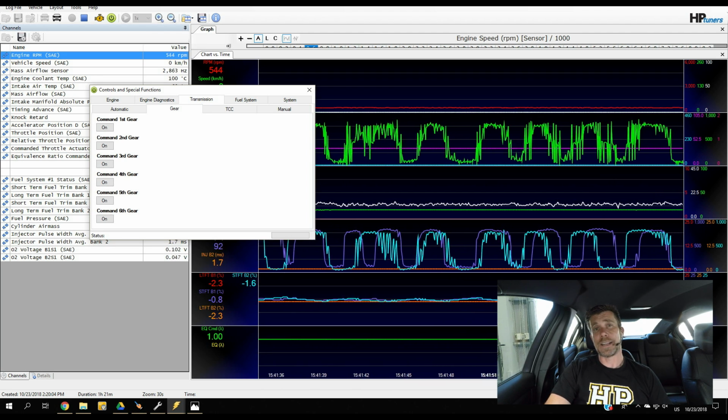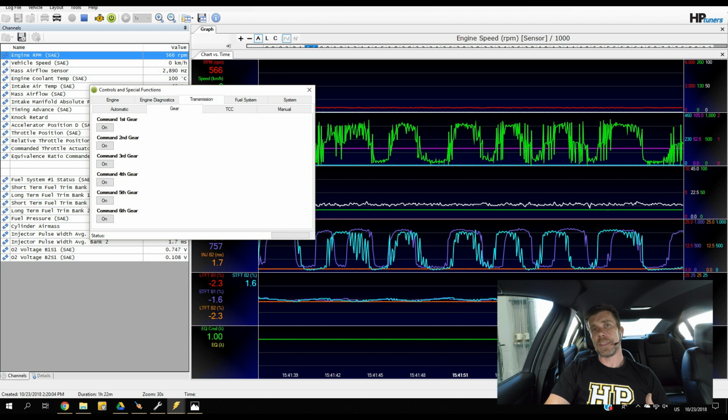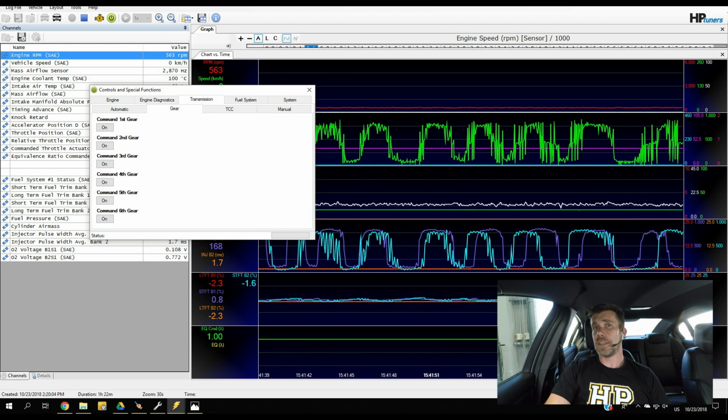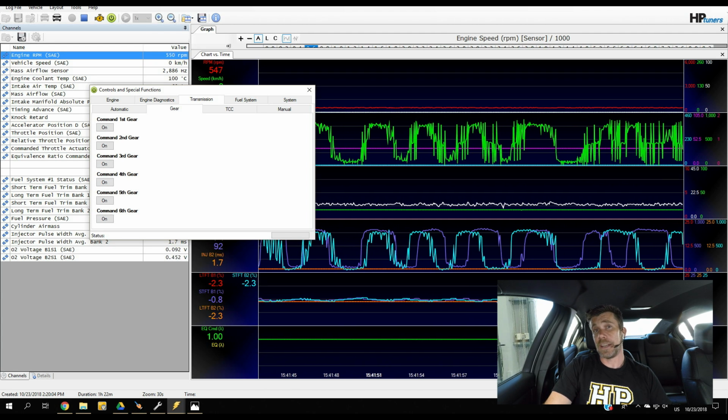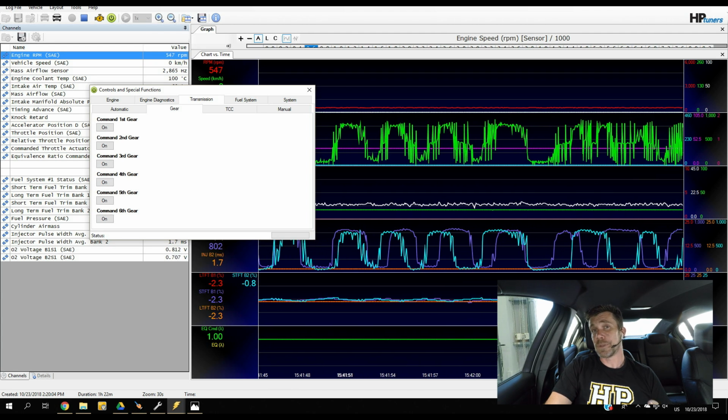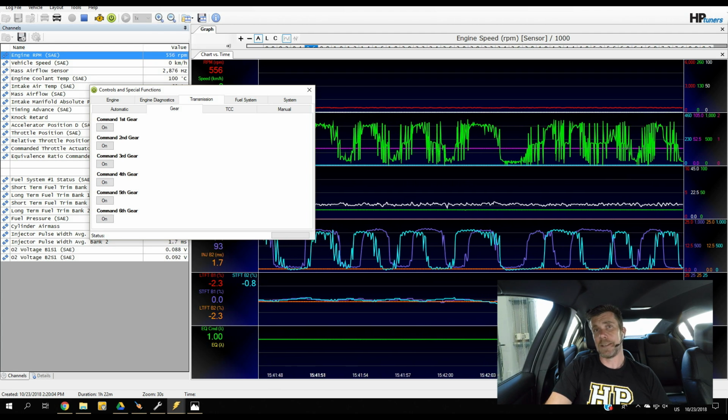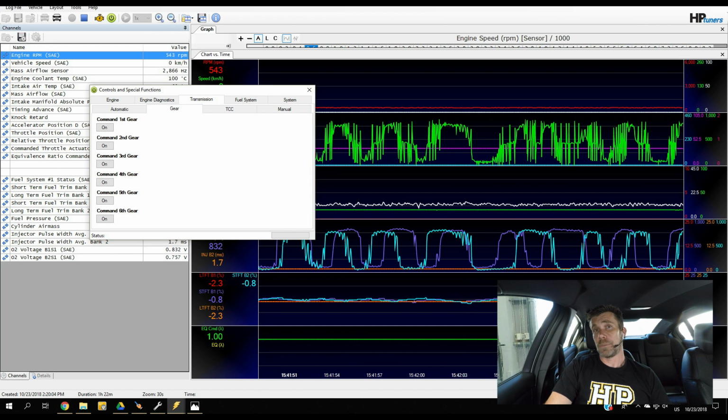You're not going to get a lot of good data by doing so. The technique I adapted was basically you can find the point, when you watch your throttle position in the scanner, where the transmission does just start to kick down, and basically that's your limiting factor.